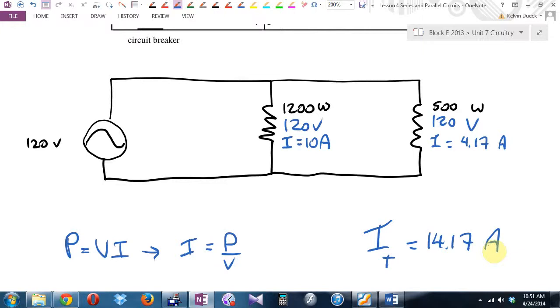That's why sometimes when you plug something in, the breaker doesn't blow right away. It takes a couple of minutes, and then the breaker blows. You're probably right at like 14.8 amps or 14.9 amps, and it was that little bit of wire heating up, increasing the overall total resistance, which we're ignoring, that put you over the top. Certainly, you could not plug anything else in.